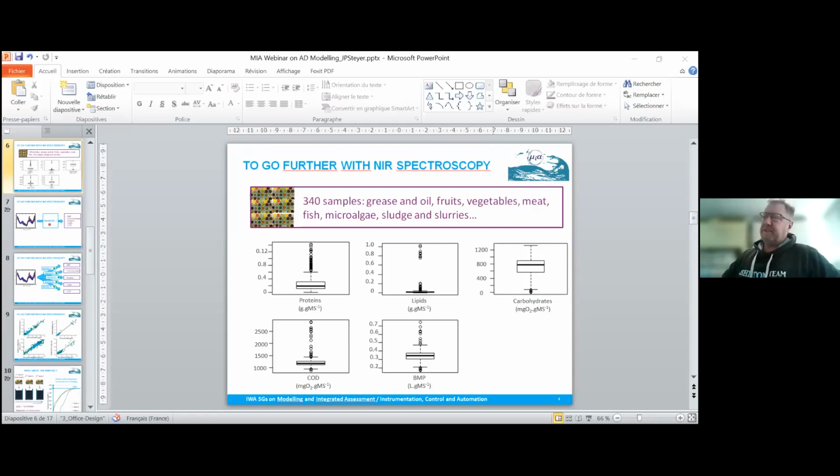In order to predict this curve, we made several attempts, and what we did at the end is we took the percentage of the BMP reached on the y-axis and divided it into different percentages. So you end up with 19 points: the time for 5% of the BMP, the time for 10%, etc., up to 95%. And so we built 19 models to predict each time of BMP achievement.